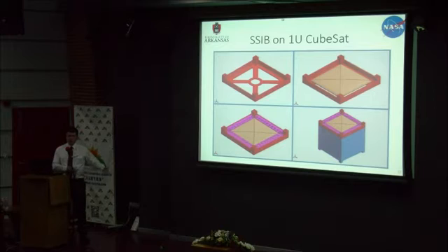What is not shown, and what I haven't talked about yet, is how to interface with the balloon from the CubeSat bus. Basically, there's going to be a wire coming out of the balloon. When we stick the PCB in the balloon and fold it up, it'll have a tail. That tail would feed through one of the holes in the subsystem frame and interface directly with the CubeSat bus. Basically the forces on the balloon are insignificant compared to the strength of a serial cable. So we envision using a serial cable, but this could be changed to another protocol with trivial effort.